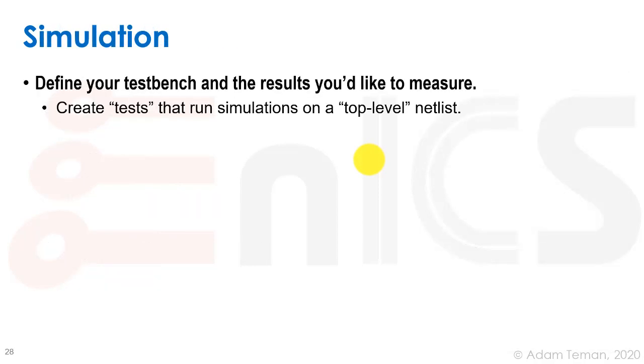Then we have our simulation tools. In the simulation tool, first of all, we're going to define our test bench, which isn't the thing we're actually going to lay out. It's just everything around it, such as the voltage sources and so forth. And we're going to also decide what results we want to measure.